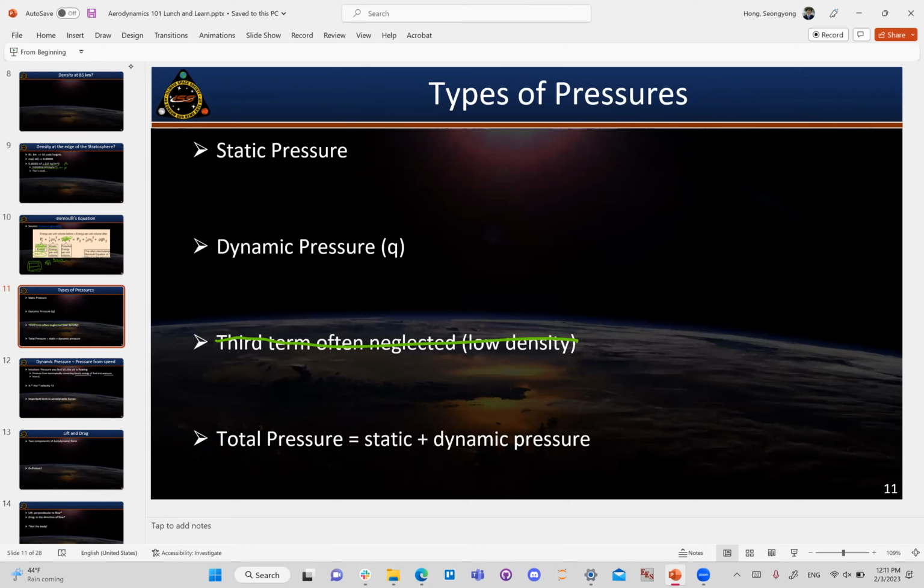And okay, so I can talk static pressure. Like I said, it's the perpendicular force you feel. So what is dynamic pressure? It's denoted often as Q, and it is 1/2 the density of your fluid times whatever the velocity of that fluid is squared. And just for nomenclature, people sometimes use V for velocity. A lot of fluid dynamicists also use U for velocity. So if you see U, just know that they mean V, velocity.